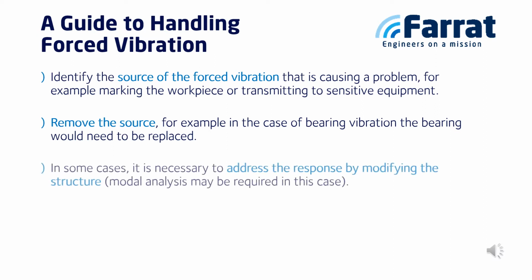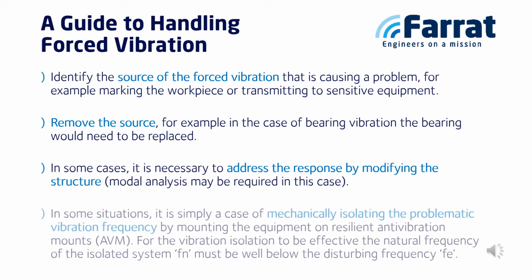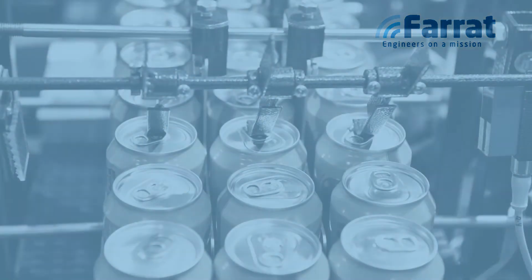Whereas in other scenarios, it may be simply a case of mechanically isolating the problematic vibration frequency by mounting the equipment on a resilient anti-vibration mount. For the vibration isolation to be effective, the natural frequency of the isolated system must be well below the disturbing frequency.